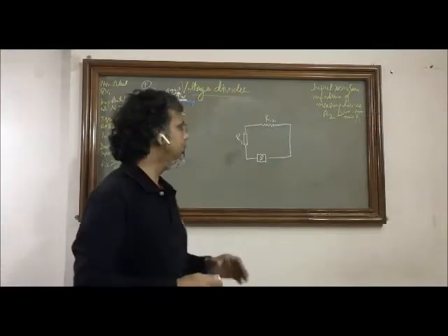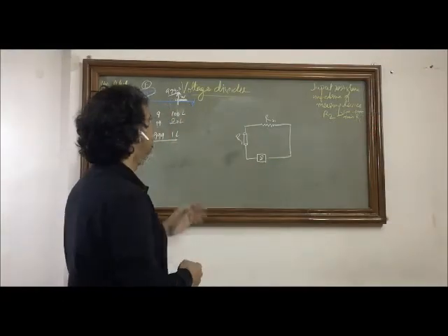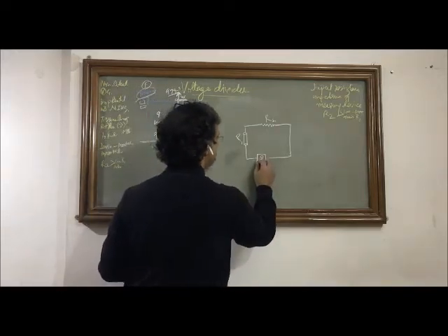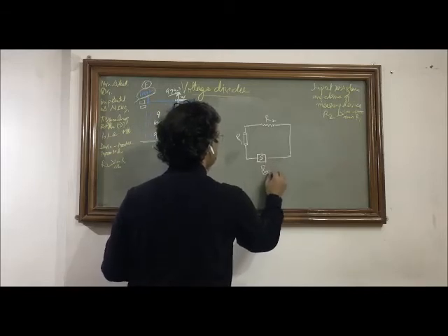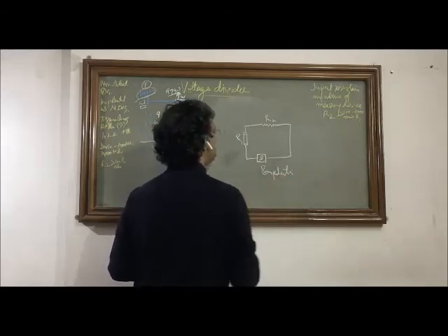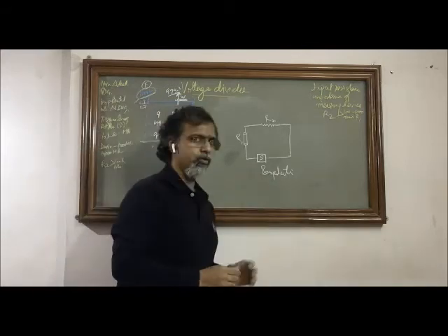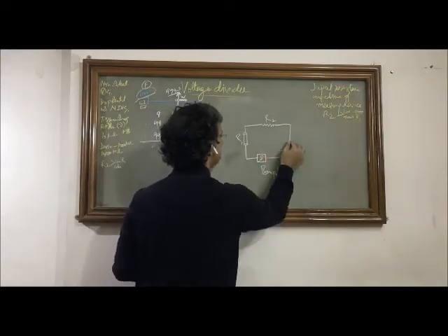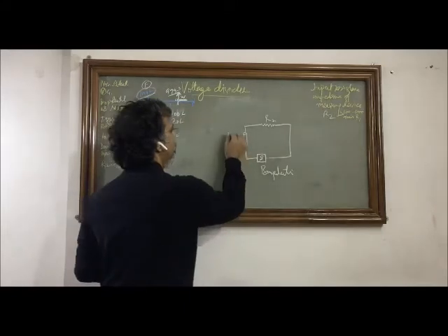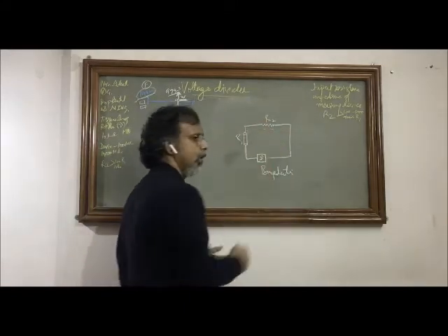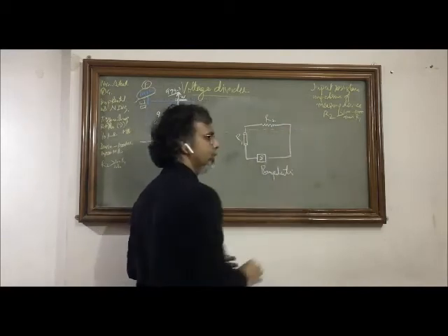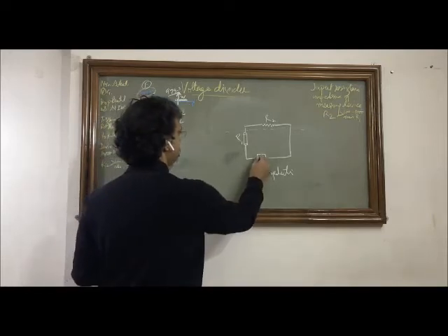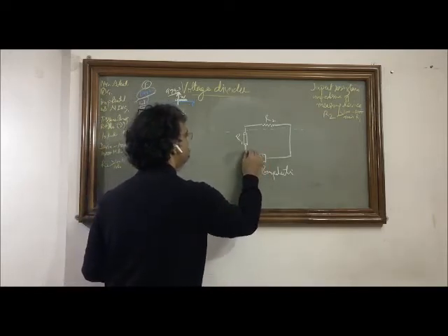So friends, let us apply this principle of voltage divider into the context of biopotentials. Assume that this is a source of some potential, that is biopotential. This can be some muscle, or some tissue which has some potential difference, and this potential difference traverses some path and comes to the skin. So let's say this is underneath and this is the skin surface. Now some of the energy of this potential difference is wasted while reaching from the depth to the skin.